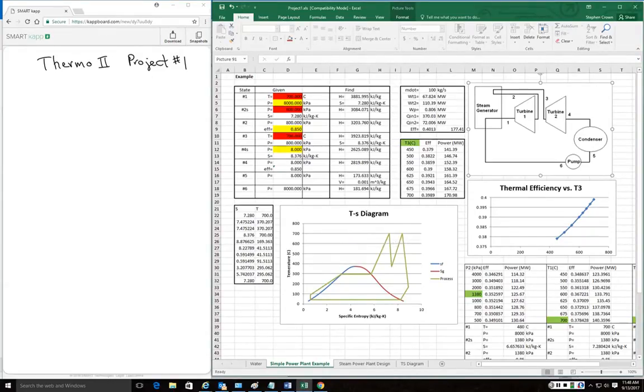So if somehow we could have, maybe done this heating with some of the reject heat, which is called regeneration, we'll probably also see an increase in efficiency, because we have this huge 600-degree temperature difference here in the boiler, which heating through a big temperature difference like that is always going to reduce the efficiency.